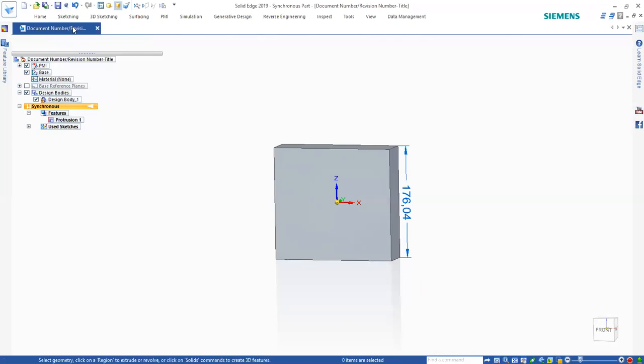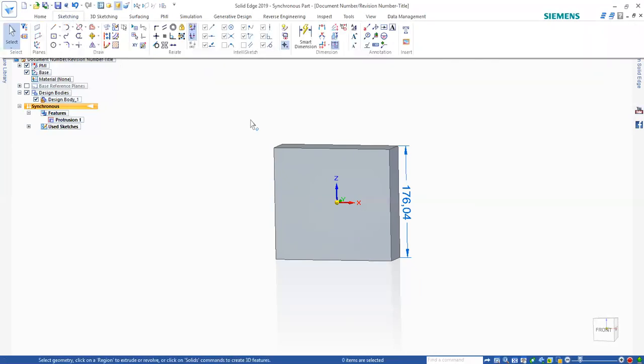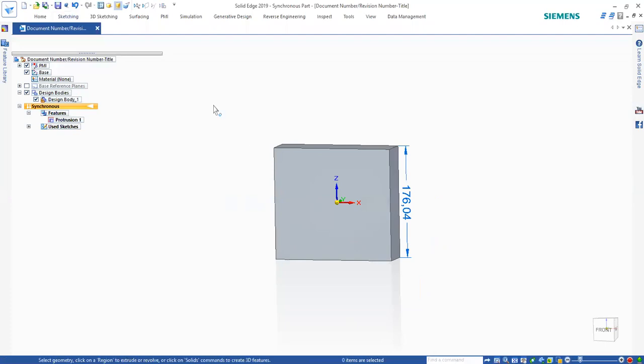Yeah. And just to mention that, I think I've already mentioned that otherwise, we do have 2D geometric relationships at the sketching level, right? You have all those available. But one of the beauties of Solid Edge is that we're not really dependent on the sketch. I'm gonna go ahead and delete this sketch. Nothing happens to my model, so we don't really care about this sketch. We edit the model on the 3D level. So you ask yourself, now you delete your sketch, you make two cutouts. How would you make the cutouts the same width?